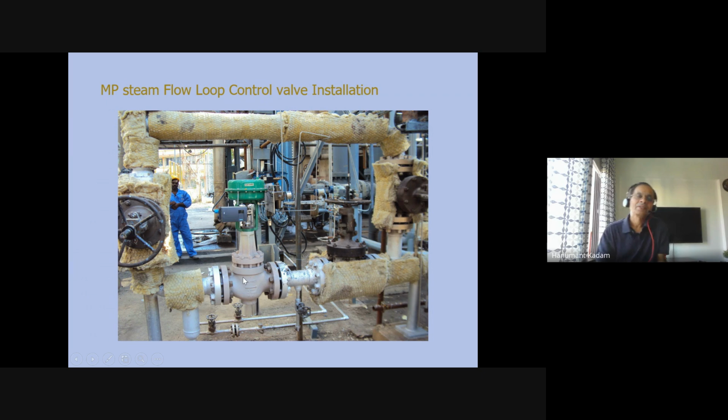Then to bring it to the workshop to calibrate such heavy equipment, a lot of machinery is required to carry the control valve to the workshop side. Small cranes, then jumbo-like machines, like a small truck type which we call in the industry a jumbo with three wheels, carry the entire control valve to the instrument workshop for maintenance.